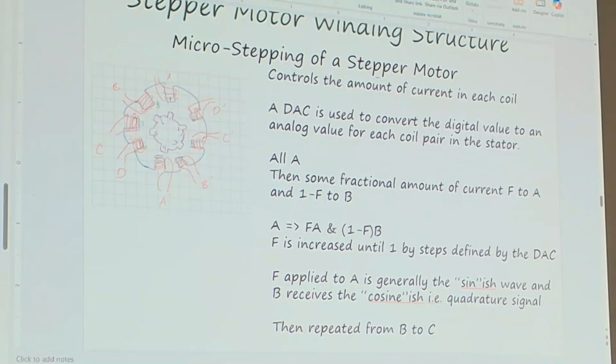That's always a problem. So closed loop stepper motors are better than open loop stepper motors. Open loop stepper motors are great when your load will not exceed the torque available. But if you do, then you have the chance of skipping steps, and you think you're one place and you're somewhere else. The only way you find out where you are is you go to some location until a condition occurs, i.e. home. Here I am, okay, now 0, 0, 0. You guys probably have done that on your printer or watch your printer.